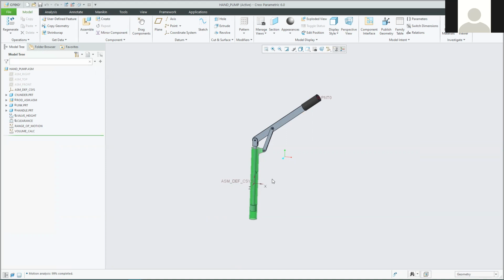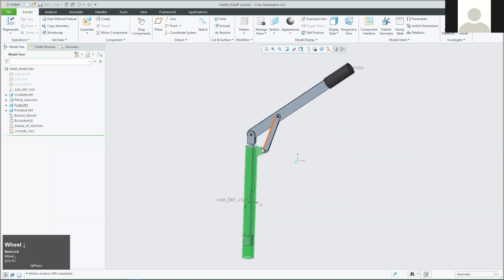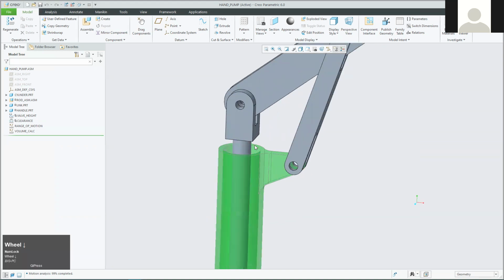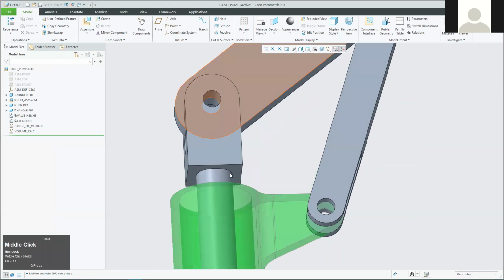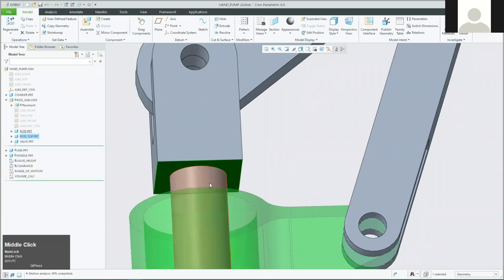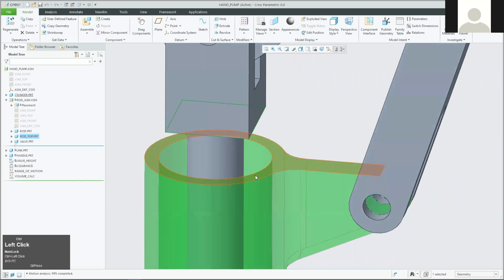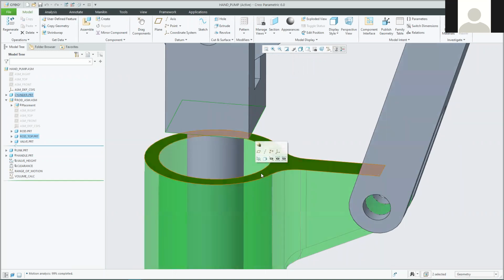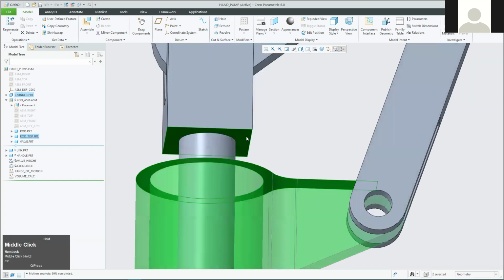We've got some dimensions that we'll put limits on, their maximum and minimum that it's allowed to vary them by. And then just as a final little rule, we'll give it a rule which says the underside of that face there cannot get nearer than a quarter of a millimeter to that face there. So there's a clearance constraint that's been enforced. So in all the investigation that the system's going to do of the values that we give it, it will keep an eye on whether that constraint ever gets violated. So do those two faces ever get nearer than a quarter of a mil within each other?